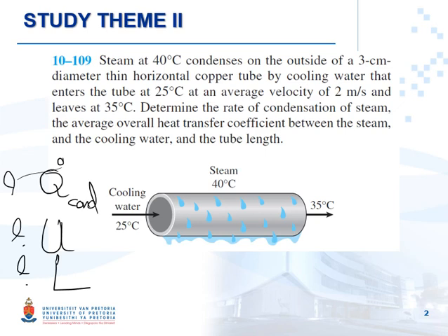The same thing might happen to you for boiling as well. Why? Because it looks like boiling, so you immediately calculate the delta T excess. Based on the delta T excess, it's very simple: find what boiling regime we are in, find the correlation related to it, read the properties from the table, and put it into the correlation. Everything will be sorted. But here it needs another kind of mentality and thinking.